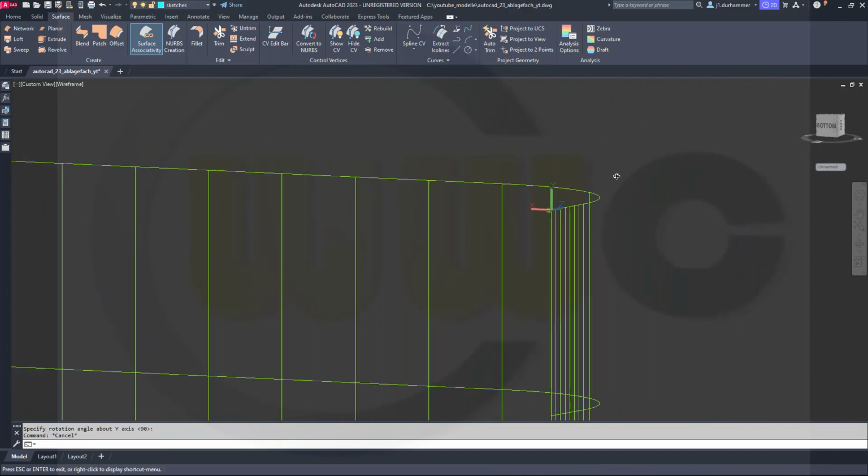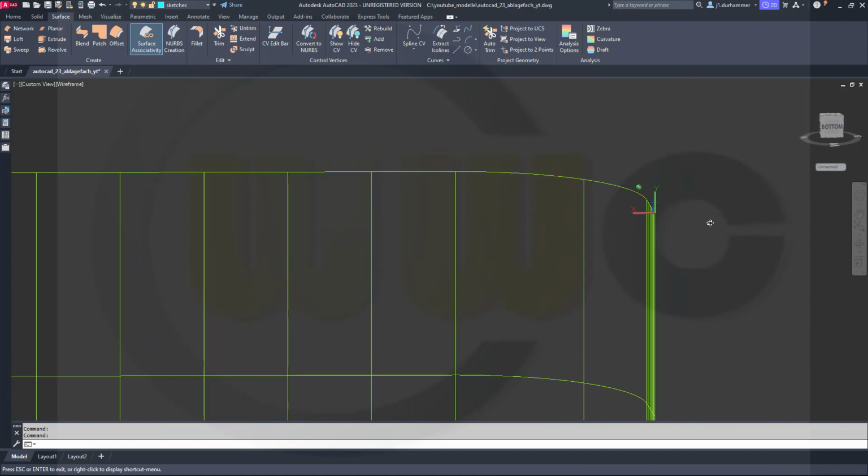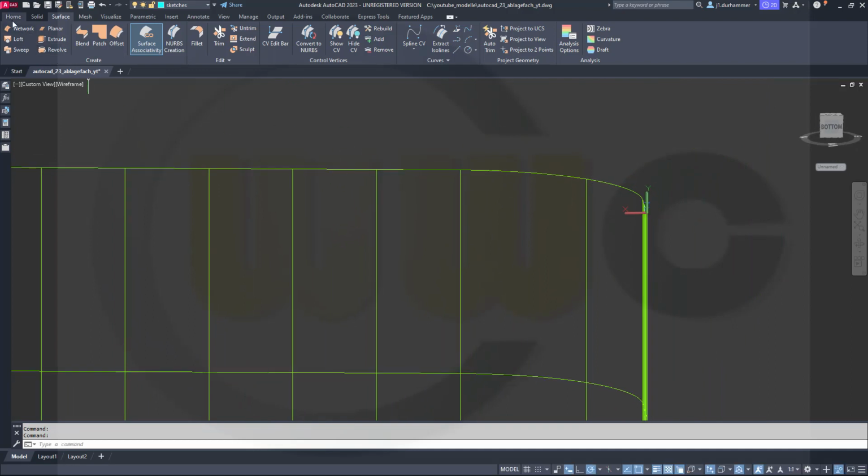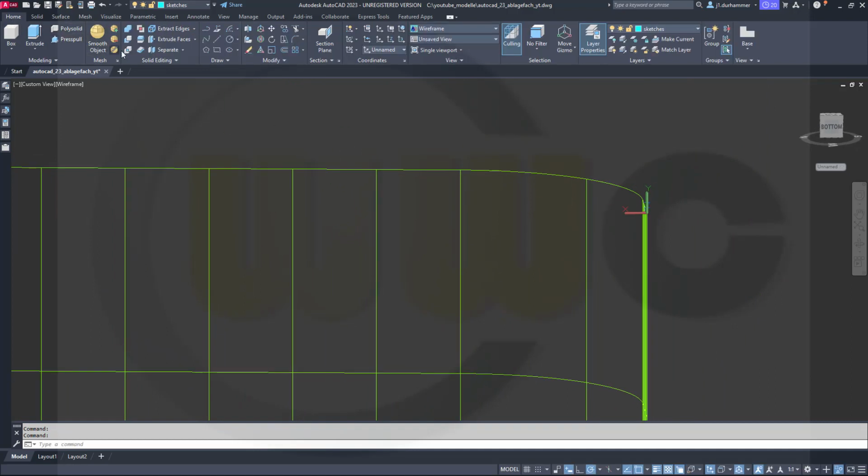And now we should be able to do here our arc. So let's go for the home tab, go for the same arc type as before. So the start point should be at 0, 0. The center point should be at 60 column 0, and the angle in this case should be 80 degrees, but to the other side that would mean it should be minus 80 degrees.